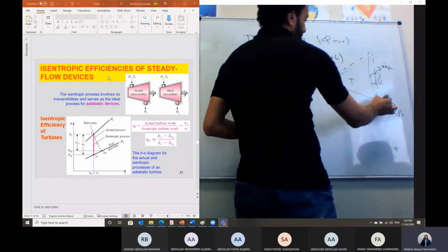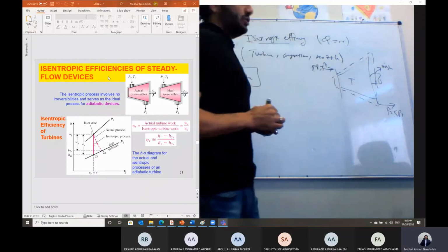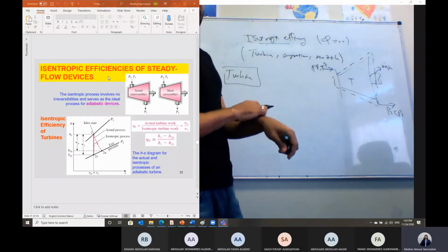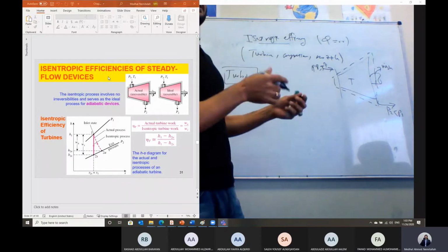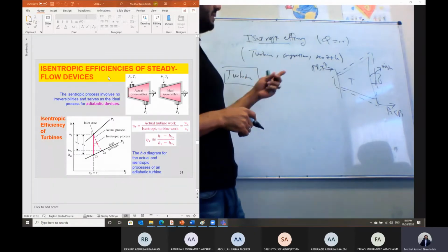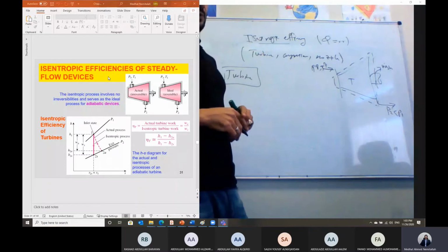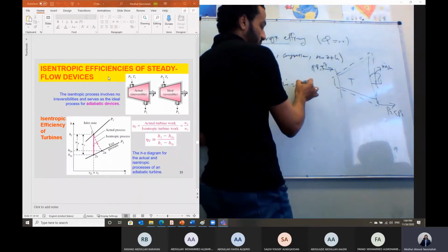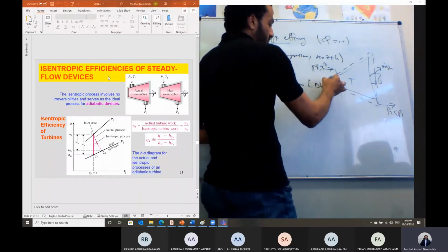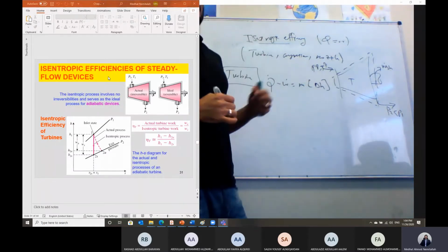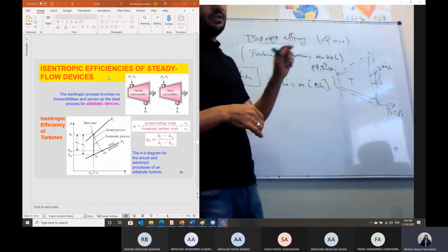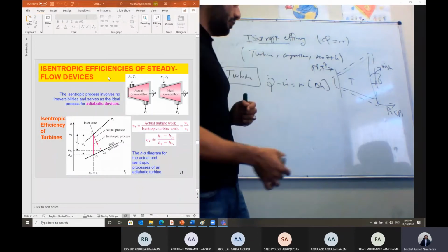Right. Let's study this turbine like what we have learned in chapter 5: draw a control volume, and look at masses coming in and energies coming, and then we can apply the first law of thermodynamics in this case to calculate the shaft power. We have gone through all of this process. If you apply the first law of thermodynamics, Q dot minus W dot will equal m dot multiplied by delta h, neglecting kinetic and potential energy, so it will be only delta h. You don't have a change in kinetic or potential.